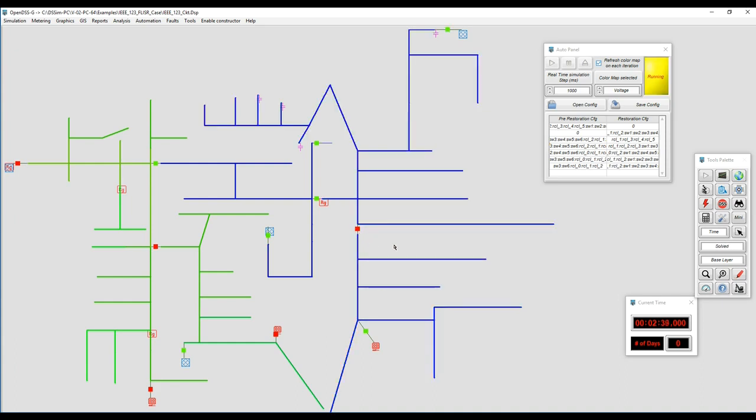So we connect, we're off. So what we can do is isolate zone 5 and try to restore zone 4 manually. And that works fine, works good. You can see where the fault was applied. And now the next step is going to be to clear the fault, restore the system to initial values, and keep going.